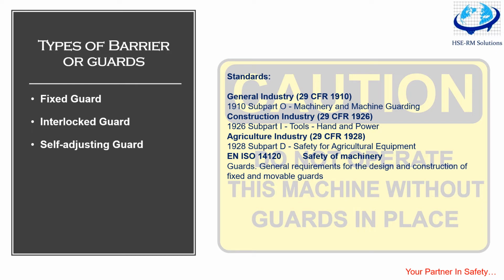To feed material, the guard size is adjusted. So for a feeding conveyor, jaws, here, to adjust the material entry, a fixed but adjustable guard is required. So understanding the purpose is important. Similarly, a fixed guard that completely separates the user from the hazard is called an enclosed guard.